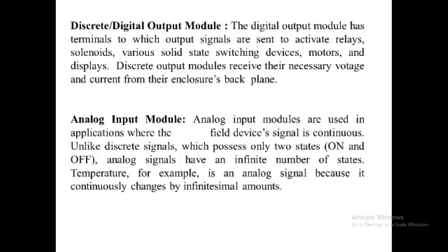Let us see here, if the output is energized, that is reflecting the presence of 1 in the output table, the logic section of the module will be latched, and this sends an on signal through the isolation circuit, which in turn switches the voltage to the field devices through the power section.